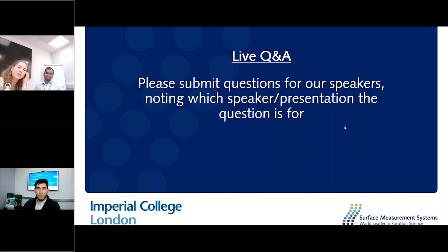Question for Ashlyn. This was by Audrey Bezrukov. They ask, thanks for the great presentation. You showed only adsorption branches of CO2 isotherms for chemisorbents. Is there any significant hysteresis in those sorption isotherms? And how would it affect DAC process? Yeah, so we did measure the desorption isotherms as well. It's just so that the graphs didn't look too confusing, I just showed the adsorption.